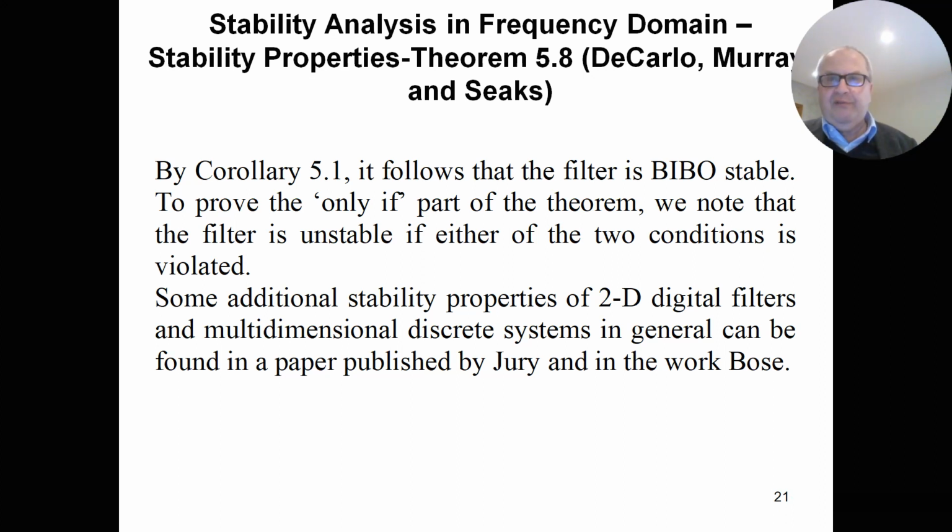And why do we have to check the stability of a filter? Because we must design a filter, and if we design a filter, from an engineering point of view, we must be sure that this filter is stable. Stable means for every bounded input, the output must also be bounded. If your filter is not stable, then from an engineering point of view it is useless. So we must have practical tests to examine stability.